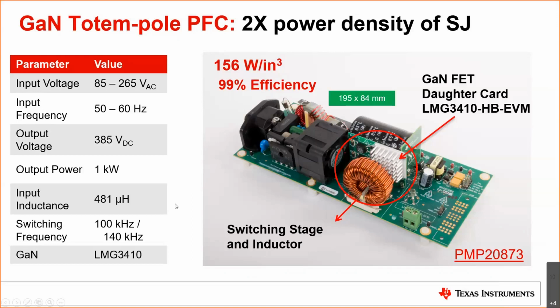And yeah, the design was very nice. It's running at 100 kilohertz, so definitely higher than what you can achieve with other designs. And the GaN switch for this design specifically is based on the LMG 3410. But to the individual part numbers and the portfolio in a bit.